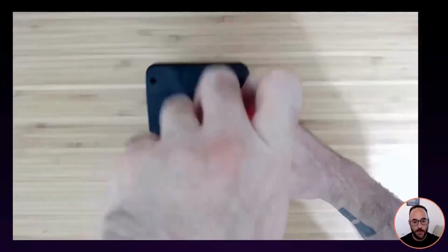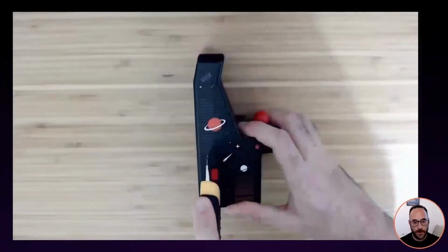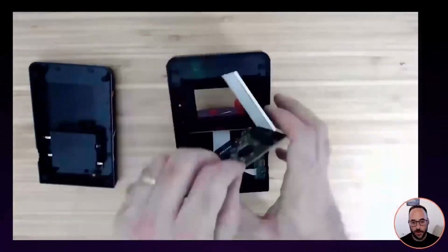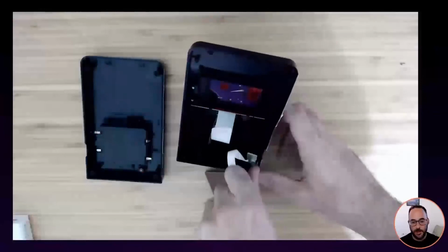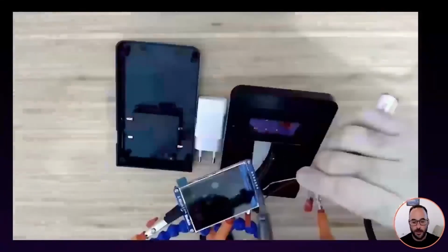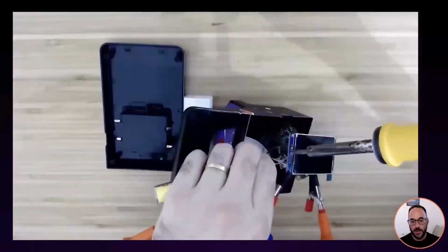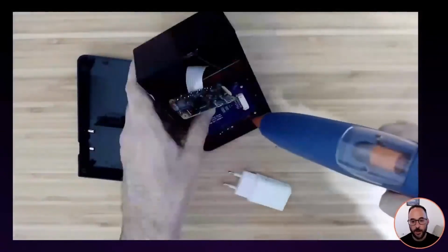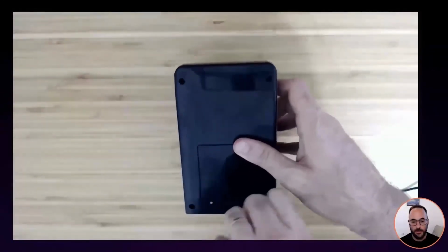Now I'm taking one of the machines apart and removing the parts that I don't need, like the original screen and the battery compartment and all that. I'm exposing the wires on the controls board, and wiring everything together to the LCD and to the Raspberry Pi, using a hot glue gun to put the LCD in place, putting the screws and putting everything back together.